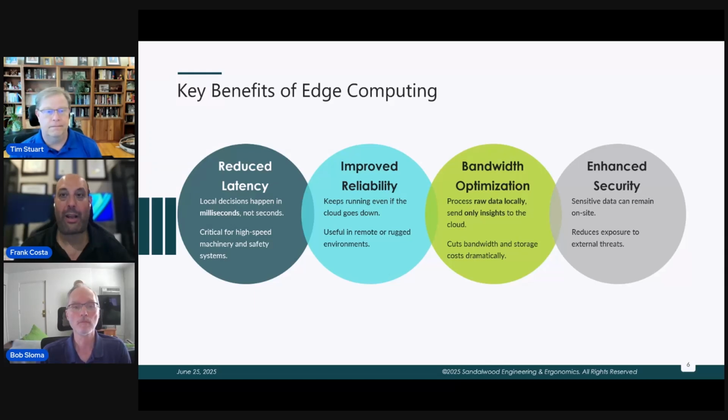Yeah, and I'll go to that enhanced security, right? Because now, to your point, especially today, you want to reduce that attack vector, that surface. So if you're doing everything on your OT network or operational technology, so we're talking the sensors, the PLCs, and whatnot, you don't have to harden all those points. You should harden all of them, to be clear. But when talking exposure to your bigger systems, especially your IT systems, you can go ahead and concentrate a lot of your work right at that ingestion point from the OT to the IT.